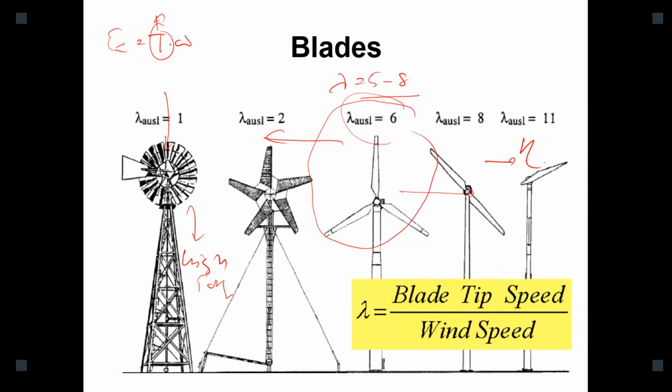Actually, we call it yaw. The yaw is the concept here. Yaw means we can orient the wind rotor to the proper direction. Generally, in all horizontal axis wind turbines, the yaw technique is there. For large wind turbines, shall I start with large wind turbines? In large wind turbines, they have a wind sensor on top, and the turbine is oriented to the proper direction from time to time. I think that is your question, Nalin?